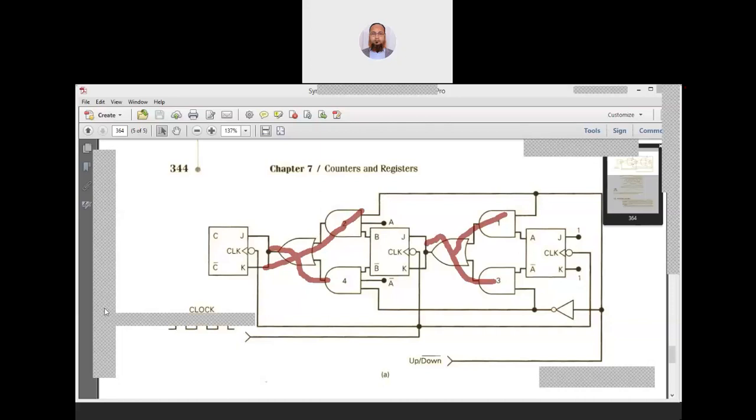Okay, so this is the case. So I told you, if we want to make the down counter directly, how we can use it. Okay, how we can use it to make it the down counter. So we remove this circuitry and this AND gate, and the 1 and 2 AND gate we remove, and this OR gate, and directly connect this 3 and 4 to the next system.